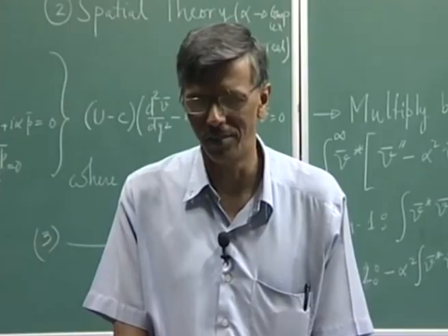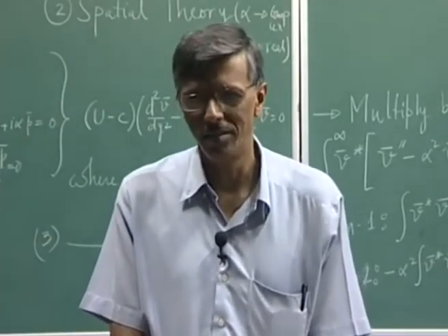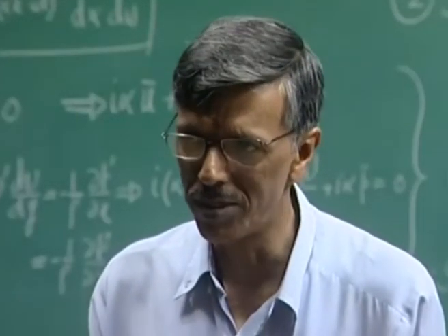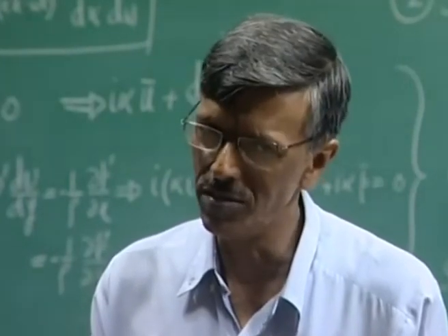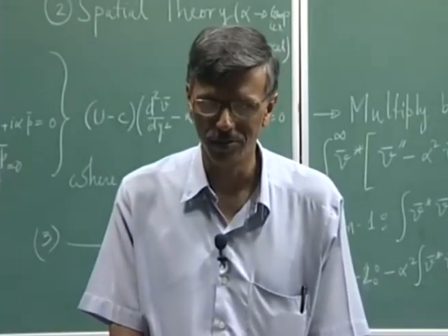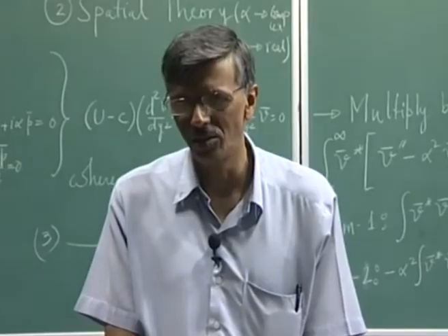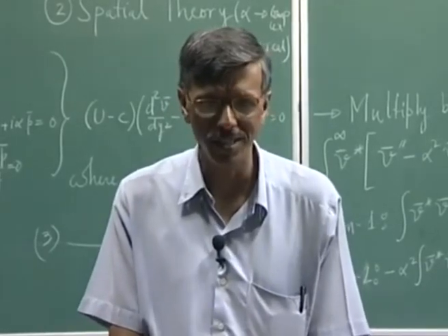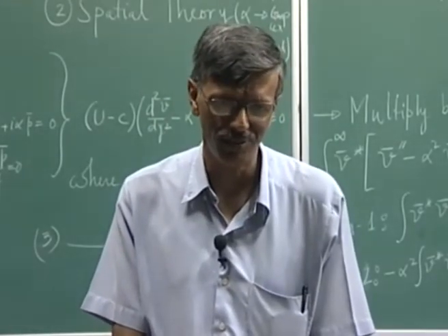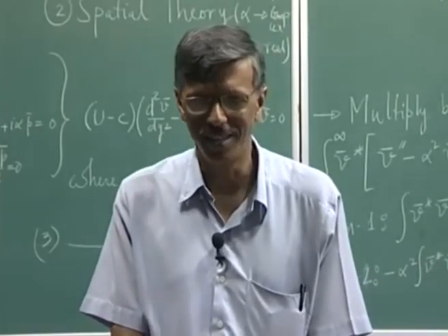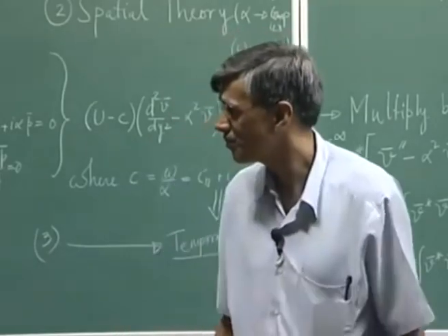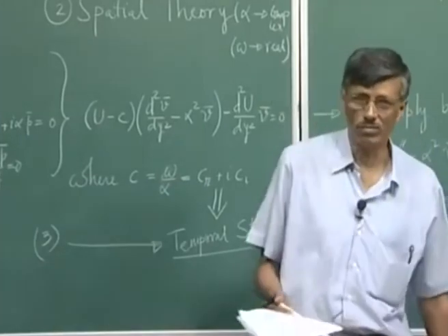How do we do it? Well, look at the boundary layer equation. The boundary layer equation is a reduced x momentum equation, and there you see the viscous term comes with the second derivative. On the no slip wall, the second derivative is related to the streamwise pressure gradient. Now, when you have a zero pressure gradient flow, the second derivative is automatically 0. So, we do not have to do anything, we can just enunciate it, and you can realize also that this is a necessary condition.